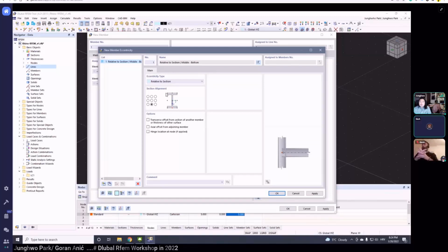And from another example, if this beam is below the slab, then you can set the eccentricity, the axis of section alignment, to the top of the slab, for instance. Usually when this beam is in the slab, we don't do this because in this case we don't have that situation. Maybe this can be useful for some jumping place, or for some high, big beams with big height.